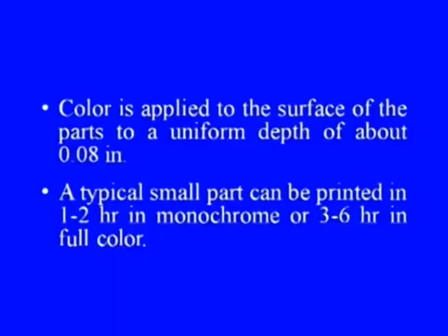Color is applied to the surface of the parts to a uniform depth of about 0.08 inch in this type of systems. A typical small part can be printed in 1 to 2 hours in monochrome or 3 to 6 hours in full color.